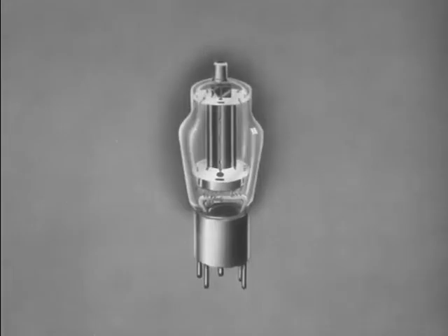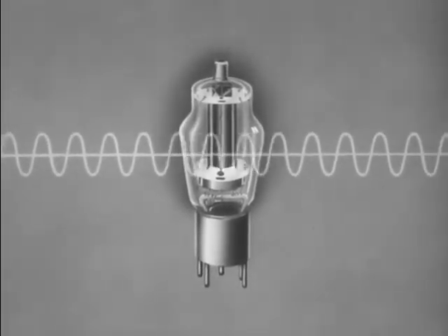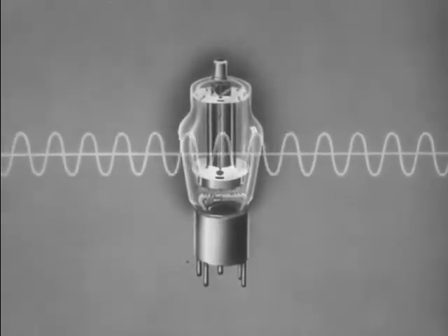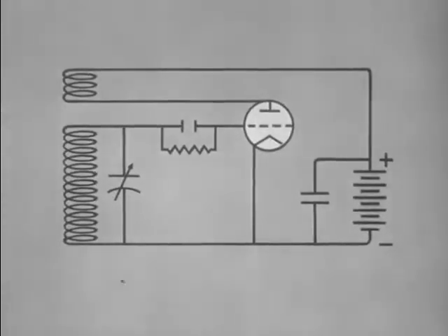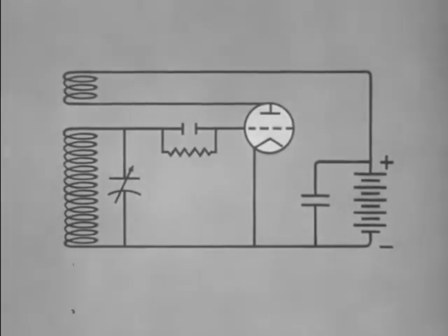However, most signal generators used in communication work operate on the same basic principle. High-frequency AC power produces the signal. A vacuum tube in a suitable circuit may be made to oscillate and generate high-frequency AC power. An oscillator is simply a vacuum tube amplifier with the output coupled to the input in order to generate or sustain oscillations at the frequency desired.